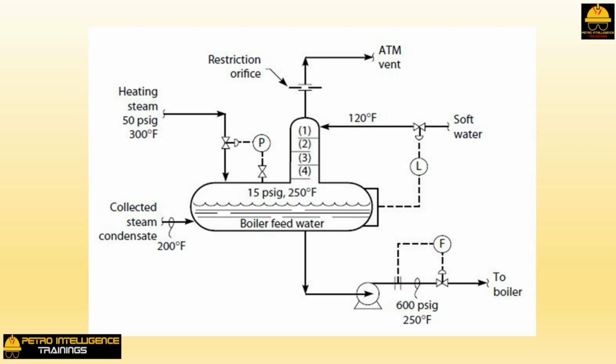The symptoms of the problem Mr. X described to me were as follows. 1. An operator working at the main boiler would open the boiler's blowdown valve. Some lime-softened water, about 10% of the boiler's total feed water, must be drained to maintain the total dissolved solids, TDS, content of the boiler's circulating water below a safe maximum. 2. This would draw water out of the deaerator vessel. 3.